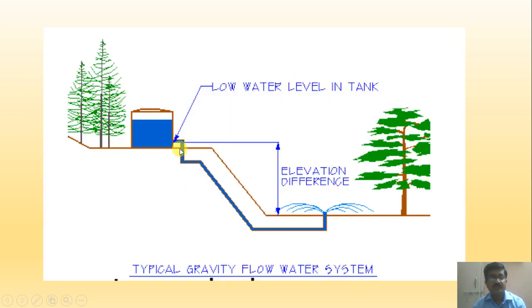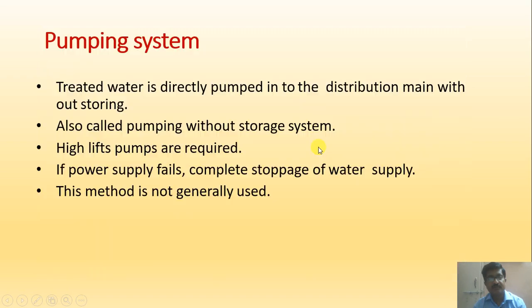You can see that after the treatment of the water, after the disinfection method, the water is stored at this particular position in this tank. Then the area to be served is at a lower elevation. It is quite possible that the water can be provided to this area by using the gravity system. This is the advantage of this system.